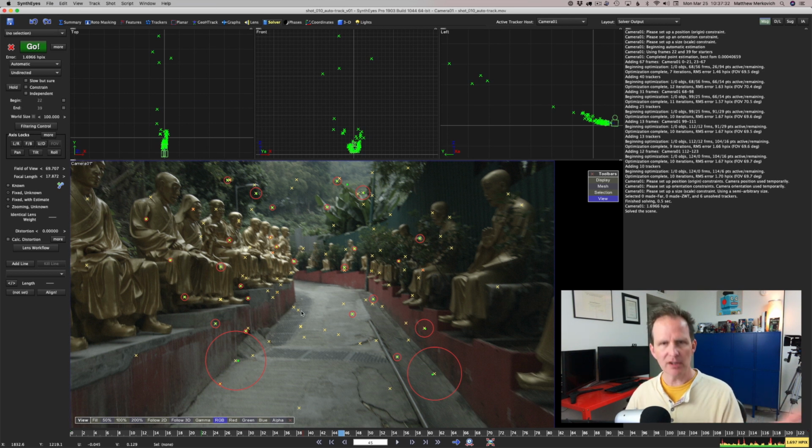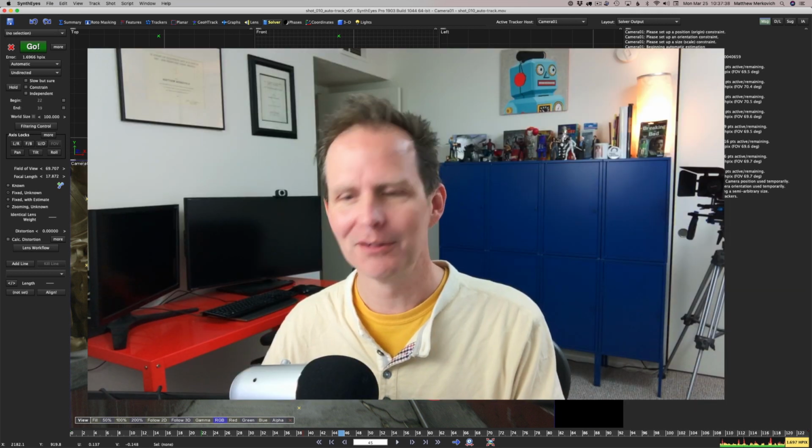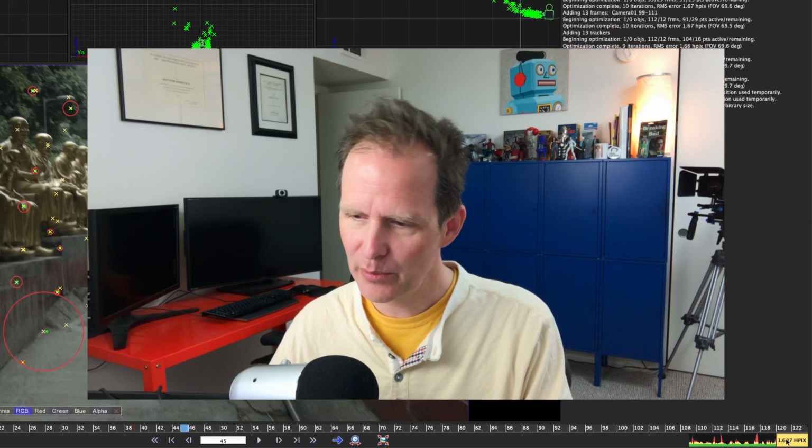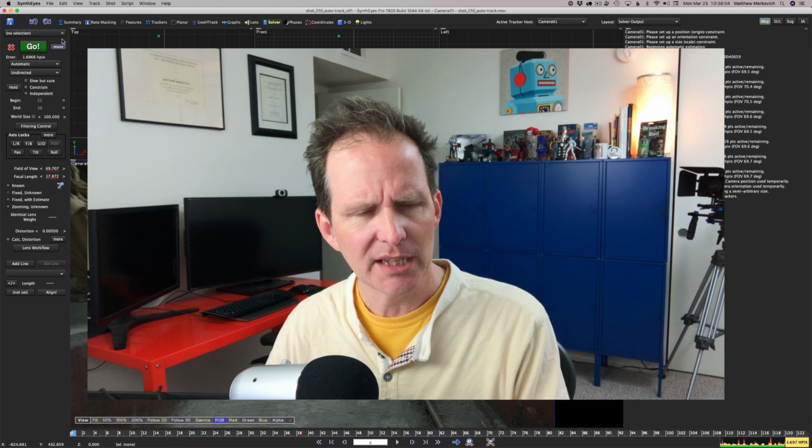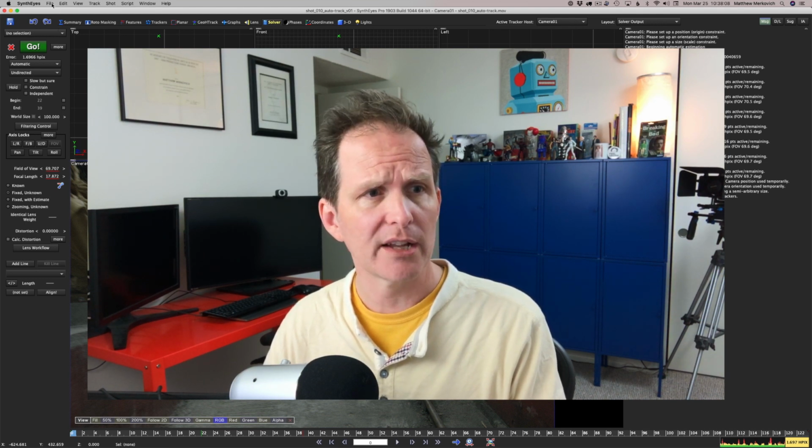All right, the shot's done. We tracked it. We auto-tracked it. Boom. Finished. No. Oh. Because if you look in the lower right-hand corner, you can see our error is kind of high. 1.697 pixels. That's not great. Let's go back to the beginning and let's just start over from scratch.